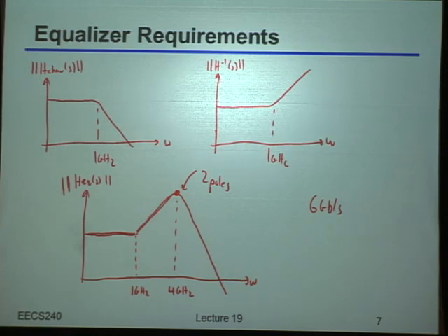So yeah, question? So you're asking, does this sort of still need to account for the dispersion? In the simple example that I'm giving you here, where I assume the channel really was a first-order low-pass filter, I'm actually accounting exactly for the dispersion, because basically the magnitude response is uniquely linked to the phase response. In general, that may not necessarily be the case, and you may have to do something specifically to deal with the phase response. That's absolutely possible.